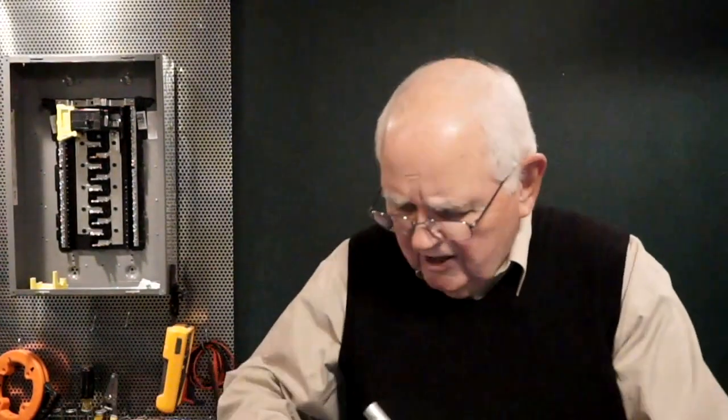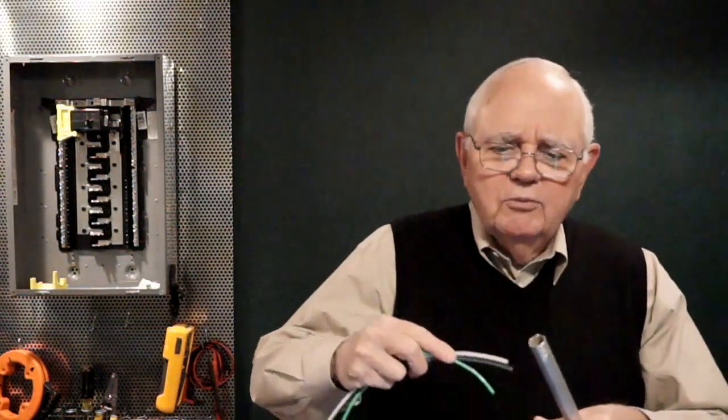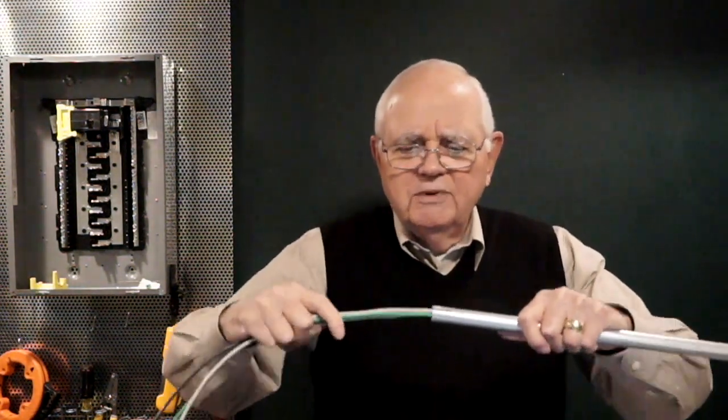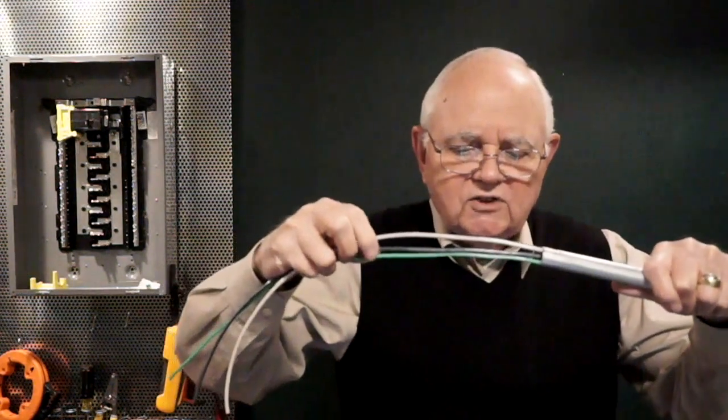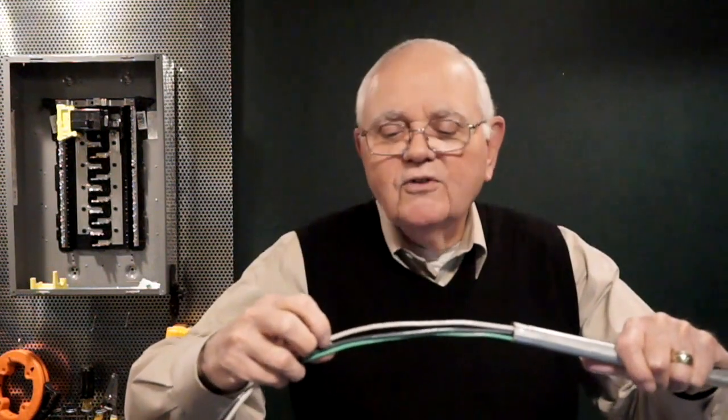So look at it this way. Let's get back to that definition we're going to talk about now on ampacities of conductors. Let's say I'm going to take some of this number 12 building wire and put it into, in this case, maybe some electrical metallic tubing. I put these conductors into the electrical metallic tubing. Now I start to pass some current through them, and so the copper starts to heat up, which starts to heat up the insulation. I'm going to go to table 310.16, which is on page 161.